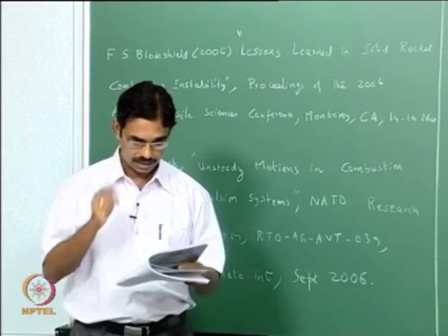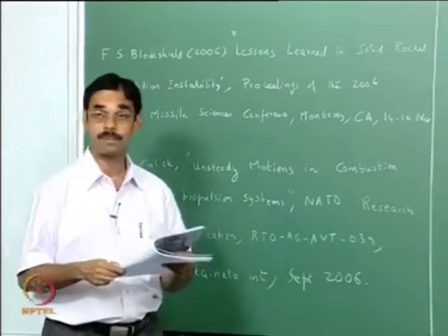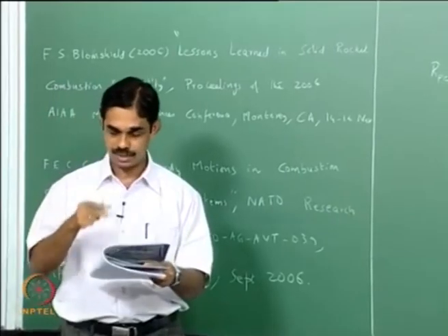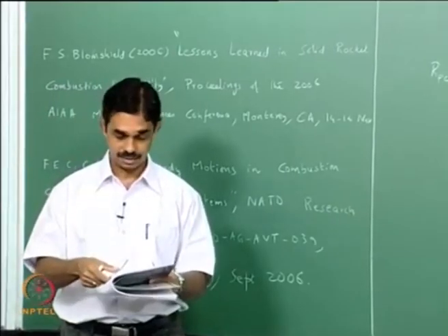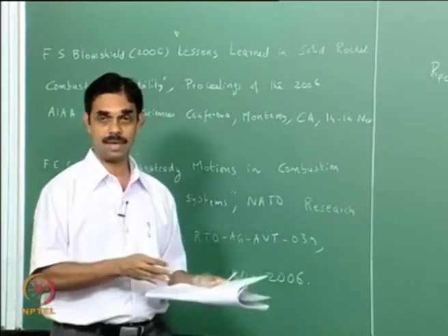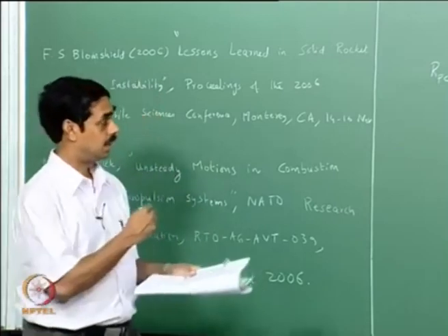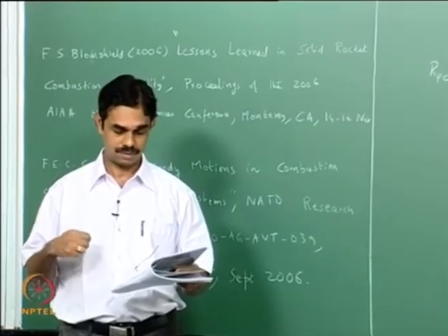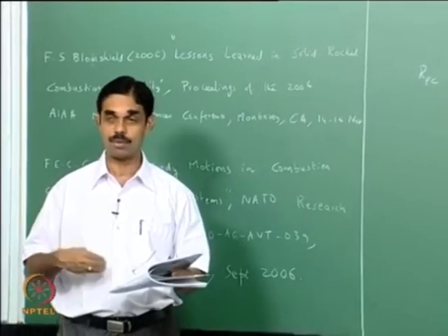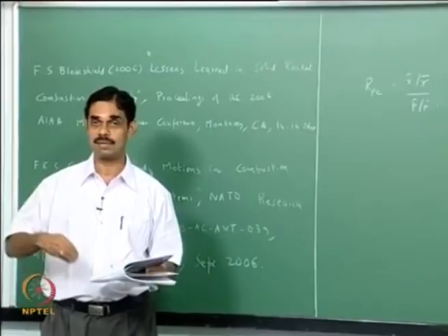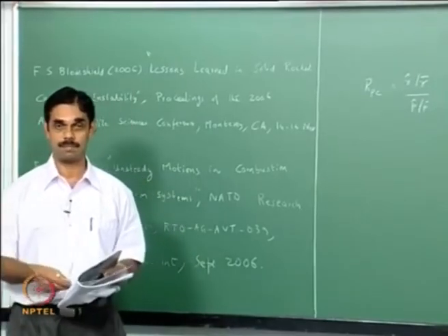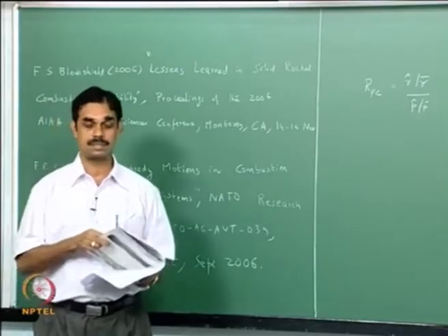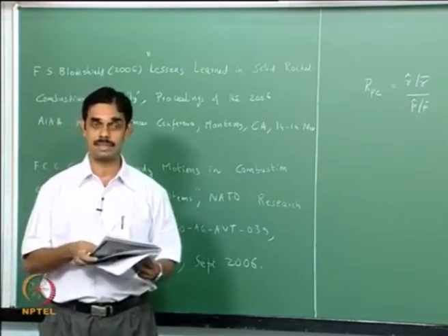Now there are many reasons for obtaining the pressure coupled response of a propellant, because primarily it can be used to compare propellants destined for the same application. So at a given frequency, if you have propellants with different RPC response functions, the one which has a lower response will be less likely to drive instability than one with a higher propellant response. Now that is one thing, so straight away it gives an idea of how much is the acoustic driving.